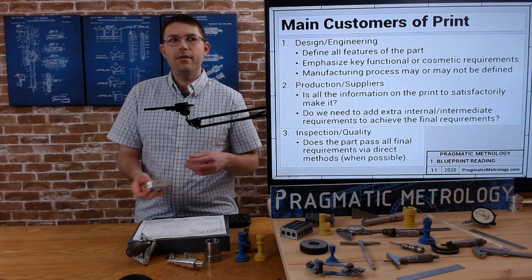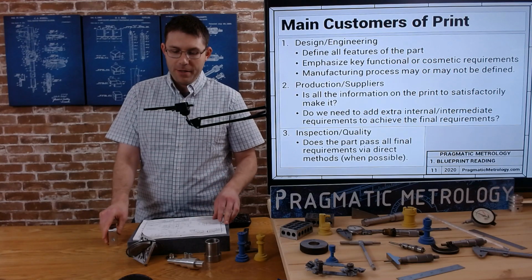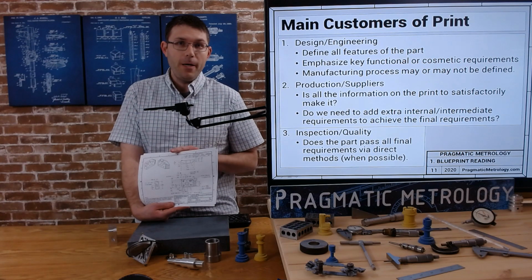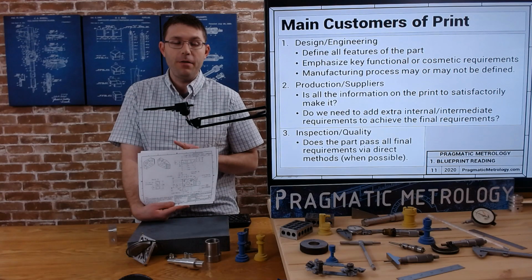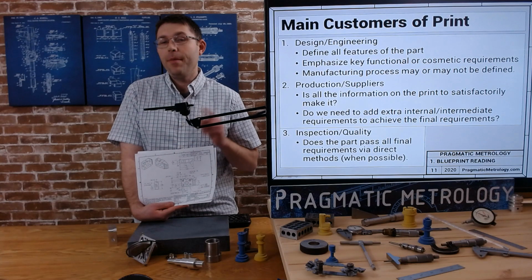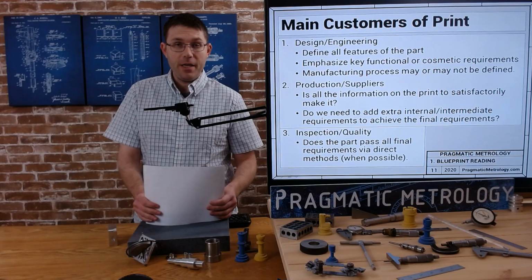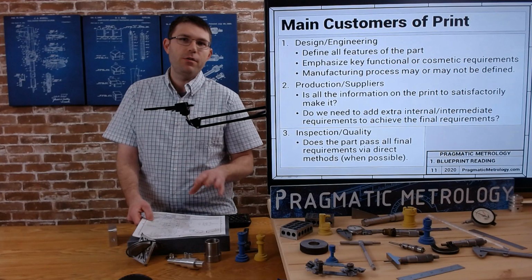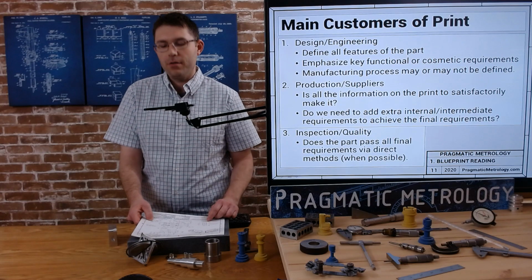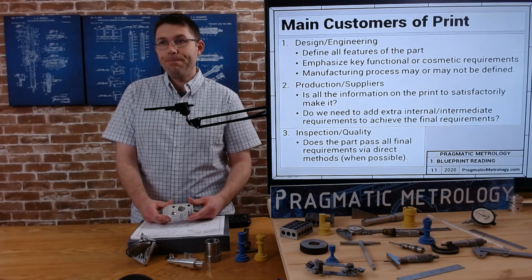And at the end of the day, when the part's finished and the function, maybe a couple of these tolerances can be opened up to allow for cheaper manufacturing. Just a couple, not all of them, but the key ones that are driving cost may not matter to the final function. So the production people are going to be thinking about that. They're going to be striving to achieve these requirements because they don't know what the part does for sure. Most of the time you can infer, but you can't know for certain sometimes.